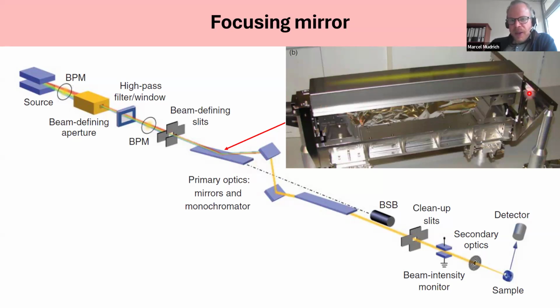They can be meters long, which of course means that the surface quality needs to be extremely high, because the beam spreads over this very long region that's shown as this yellow elliptic profile here. So very high surface quality in terms of roughness and wobbliness, and also very high surface quality in terms of curvature, if this is supposed to be a focusing mirror. And we will come to these focusing mirrors in a minute.